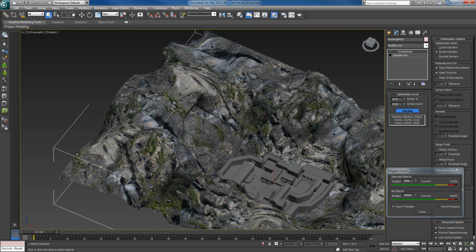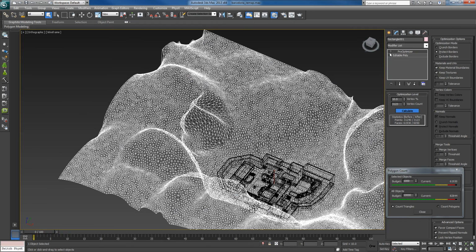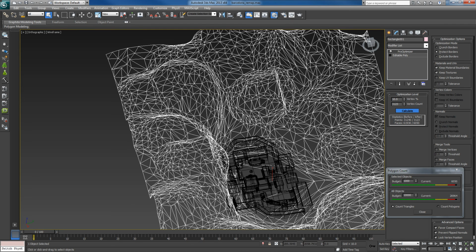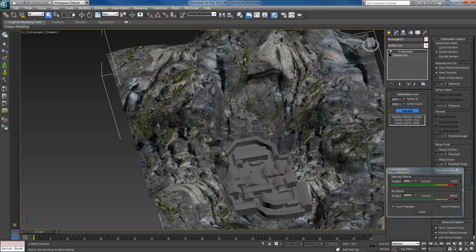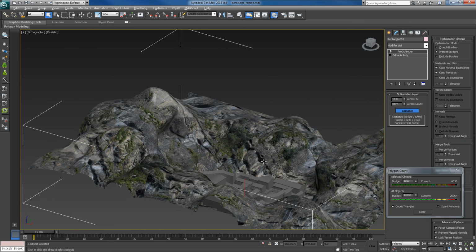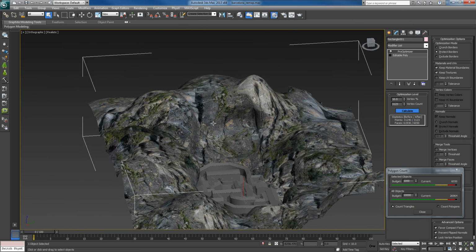Okay, if we look at the wireframe, we're at too much, down to not enough. The reason we're able to maintain the overall consistency in our geometry is because we used a soft body material to define the shape and form. If this was polygons, right about now this little peak here would become a peak. It wouldn't have maintained this type of smooth translation. See, it loses some shape and form, but I wouldn't say it's good, I wouldn't say it's bad. I would just say it's different.